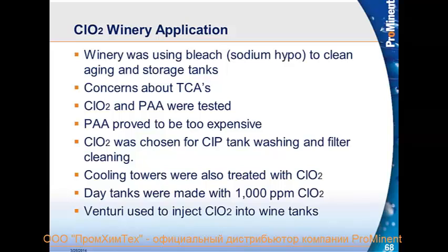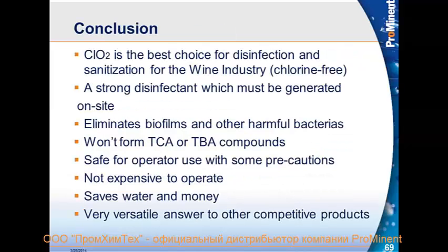They also decided to use chlorine dioxide to treat their cooling towers. And they had day tanks that were made with 1,000 ppm solutions of chlorine dioxide. And then they used the Venturi to inject the chlorine dioxide into wine tanks for cleaning. So, a great application. There are many more out there. This was just one of the ones that I chose to go through with you. If you need more instances of applications, I have those available.